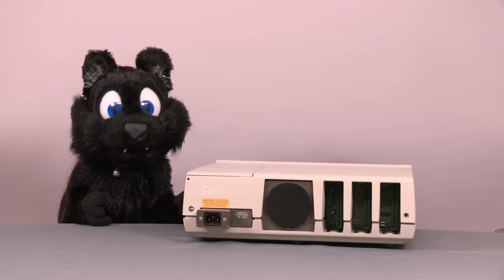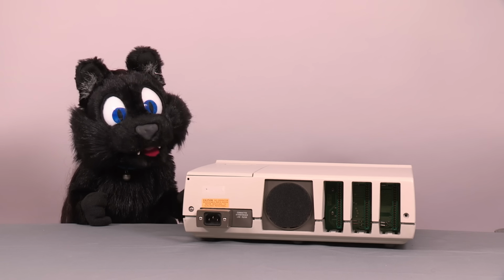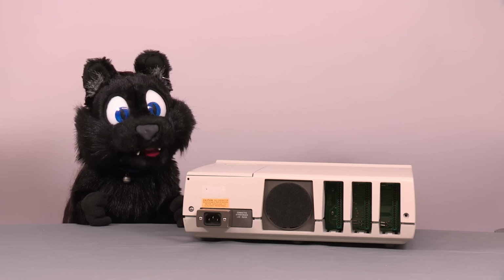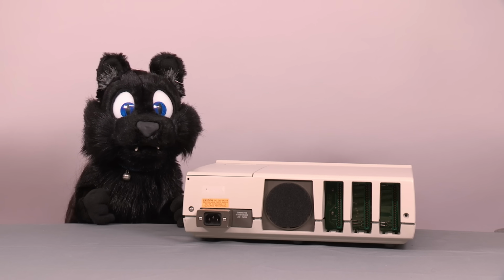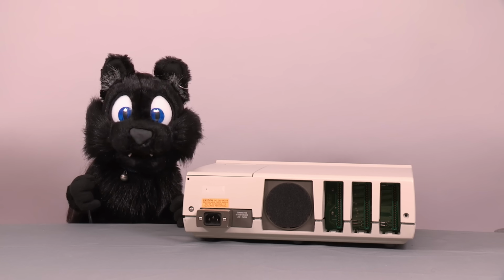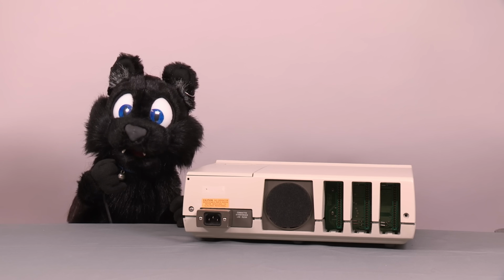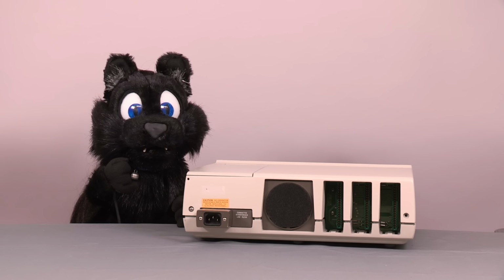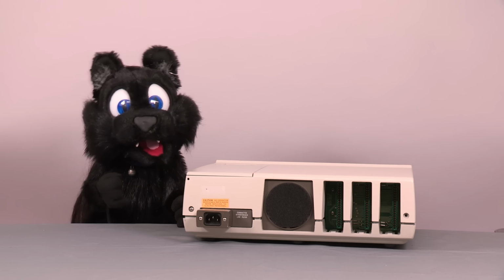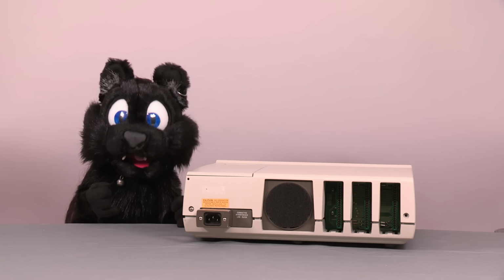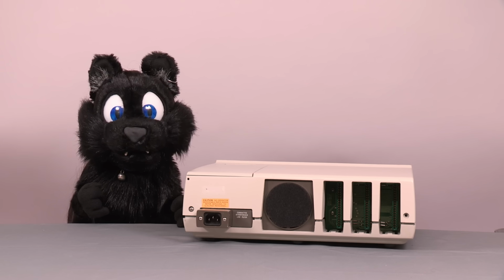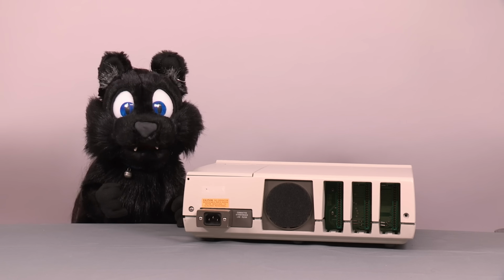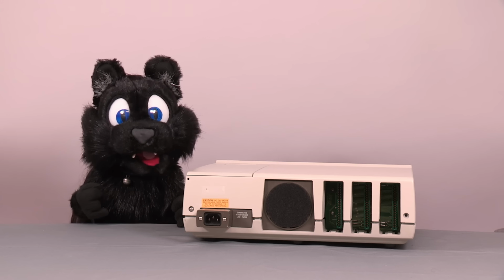The second part of the update is about future hardware tinkering. The strength of the 9825 are the expansion slots for different I/O solutions. But of course, there are no new ones coming out from HP anymore. So, how about making your own? Seems easy enough. There is the I/O bus, some read-write and status lines, and even the address lines aren't multiplexed here, since it's only 4 bits for 16 devices total.